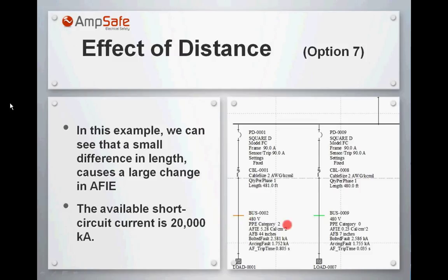That's why they distribute the panels. You have several power panels, each covering the loads of a certain area. So it's normal to have 30 foot, 50 foot, 100 foot, 150 foot, but everything over 150 foot is probably going to be fed by another power panel. So yes, you can have an incredible amount of change, and you have to be concerned about that. But remember that changes only occur when you have very long distances, okay?